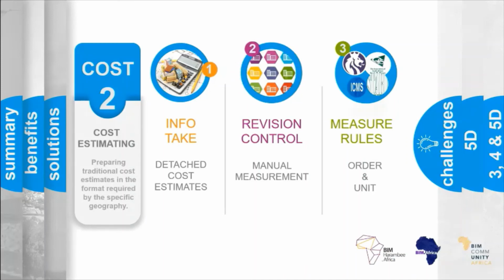Revision control is therefore very difficult to manage when the quantity surveyor is adding content to a model that is detached from the design team's workflow. This is where we must look to start, and where most of the impactful contributions by a quantity surveyor can be made. The quantity surveyor needs to be able to apply data directly to the 3D model and must provide direction on modeling of objects to better match the construction required in the real world and the method of takeoff required for that specific geography.